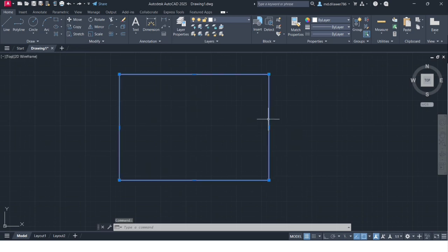Now we have successfully drawn this one box. If you want to highlight the box, simply use the object line. It is still visible only lighter, not thick. I will tell you one command you need to use here to differentiate the different lines. I will draw one object here using the object line. First I will use the object line, then the L line command. You can simply use line, otherwise L enter. See, the command is activated, L enter.